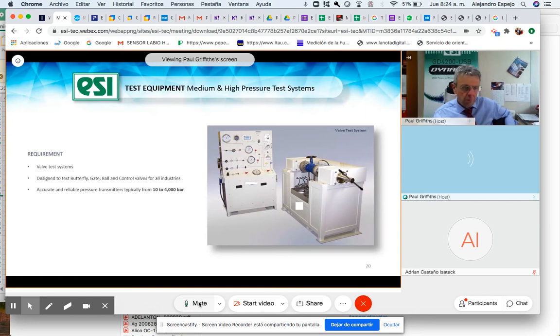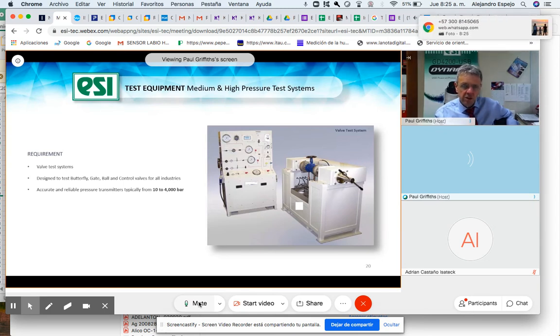So for certain pressure ranges, we have this welded titanium sensor. So there is very little risk of any leakage. The welded sensor is a very secure device, and the titanium diaphragm is very, very resistant to pressure spikes.